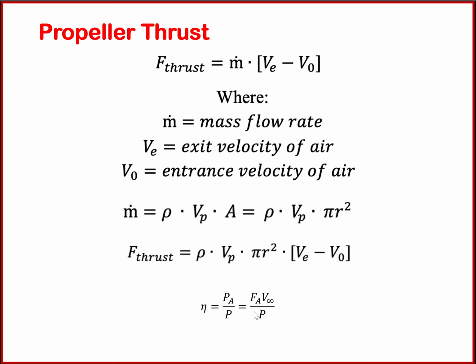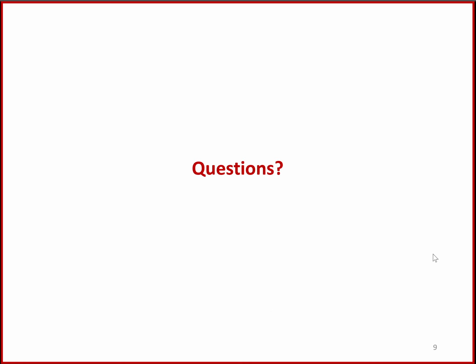So essentially we have to measure the power that is provided by the electrical outlet to the propeller. This comparison is going to tell us how much of the power given to the propeller is actually converted to the thrust force. It is converted to energy of the air, right? This is going to help us find the losses of the system.